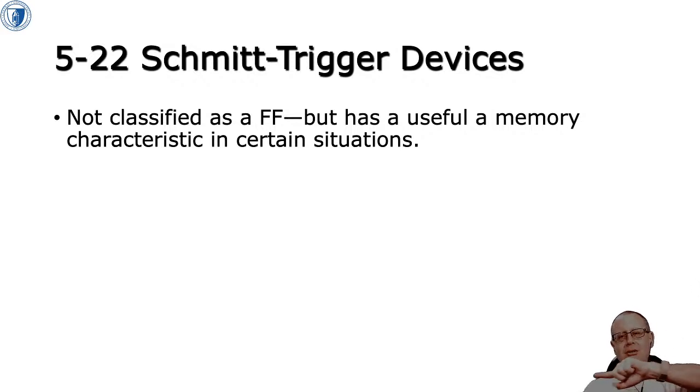When really, remember, we don't have our signals going abruptly, right? We have the change happening gradually. And if that change happens gradually with a bit of noise, then as that change in voltage goes through the threshold, determining the difference between a 0 and a 1, you get chatter, right? You get the output, or the assumed value of that voltage, going between 0 and 1.